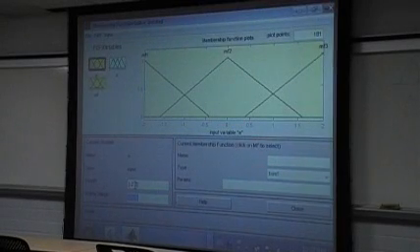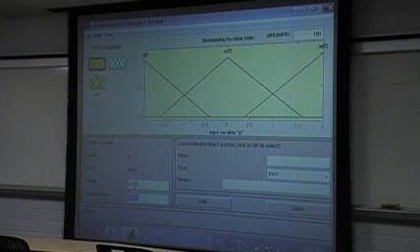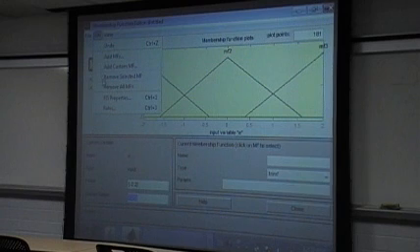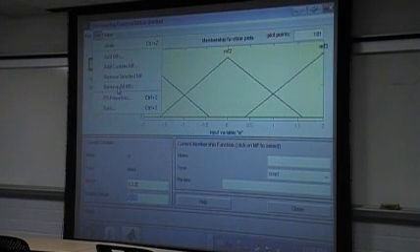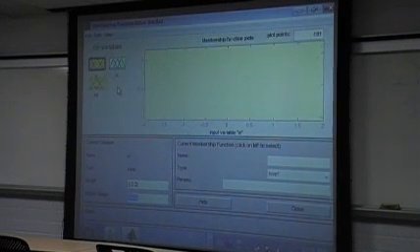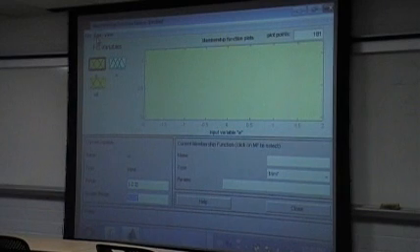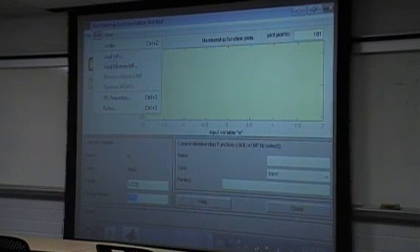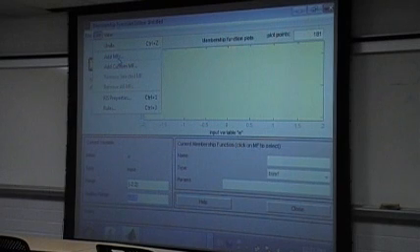In this interface, we have only 3 sets. So the easiest thing is to delete all the three sets by clicking remove all MFs. The MF stands for membership function. So we can remove them first, and then we can go to this menu again by clicking edit, and then add MFs as membership functions.